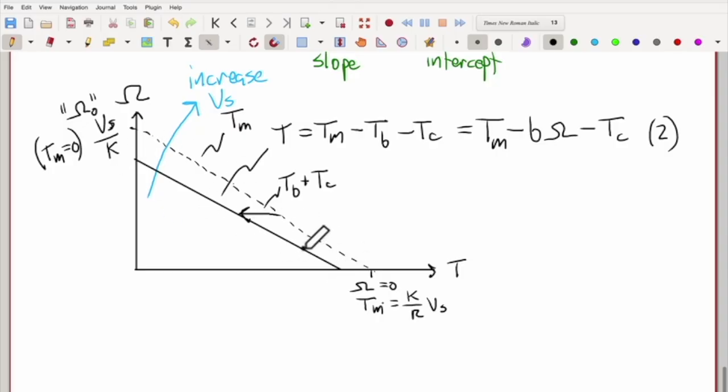So let's now think about what this looks like. This is a continuum of torques and speeds that you get for a given voltage here. So for example, over here, imagine you have the motor spinning like this. This is when the motor is stopped. So the motor's stopped, and this is the max torque it can apply here. Imagine you turn on the motor, but you're holding the axle still. This is the stopped condition.